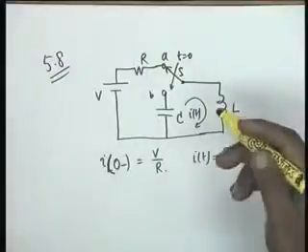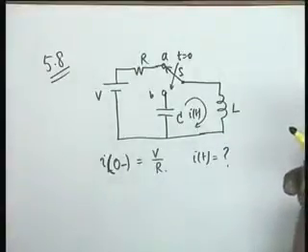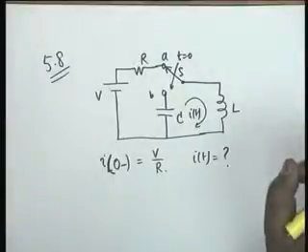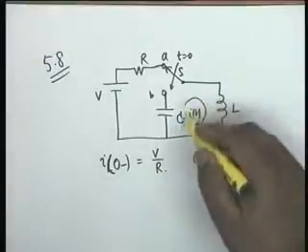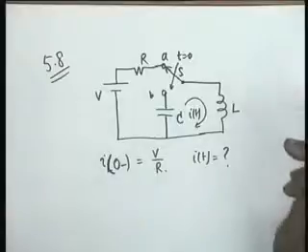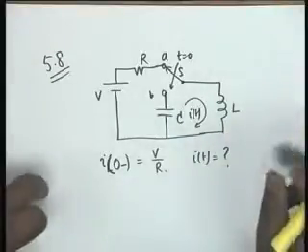How come it is able to generate oscillations? How can it behave like an active circuit? Well, in practice it cannot, because an ideal inductor is a dream element, so is an ideal capacitor. There would be resistances, and therefore what you will see in practice is a decaying sinusoid, but in theory it can be a pure oscillation.